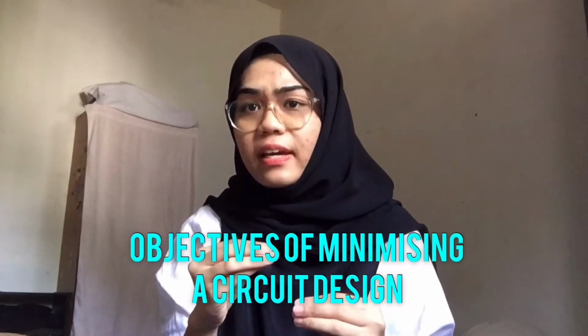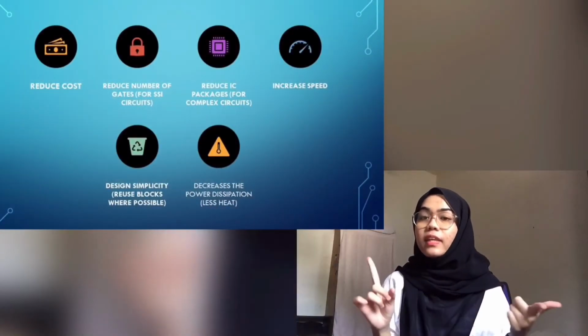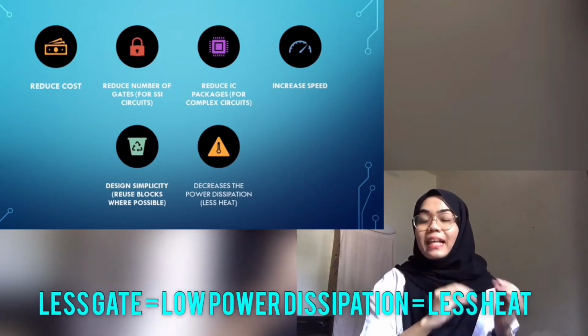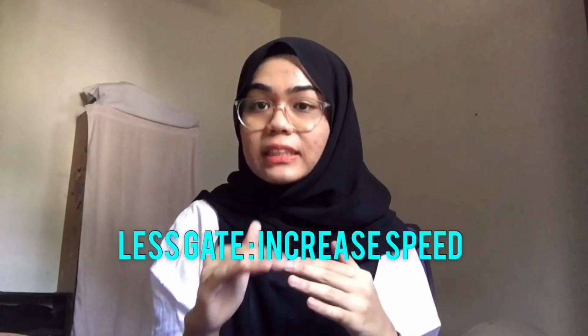Next, we're going to look at the objective of minimizing a circuit design. A circuit design can be really complicated when we combine different types of logic gates and different types of ICs. A simpler circuit design is more desirable because it contains fewer gates. When we use the least number of gates, first it will reduce the cost of the hardware, and then it will decrease the power dissipation, which means less heat will be produced. And the most important part is that it will increase the overall speed of the circuit.